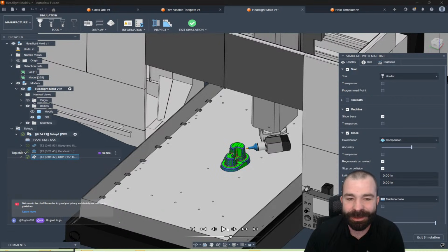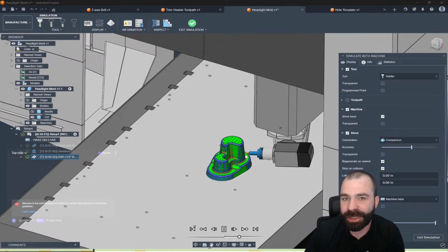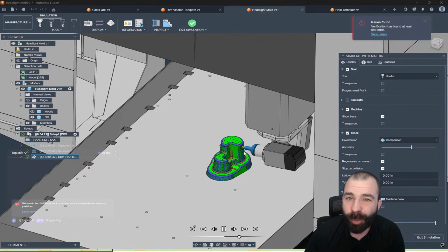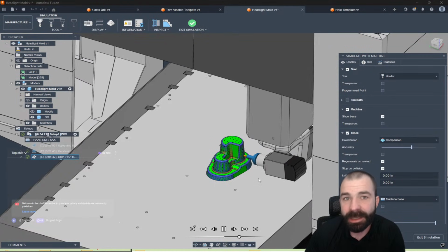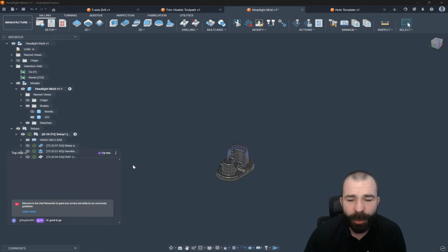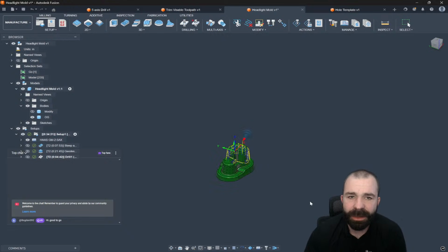We might just need to slow her down a little bit and hit the play button and let it do its natural thing. But what I'm looking for, as you guys can see, is we're not actually going all the way back to a home position, reorientating and coming back in. Dropping your cycle time quite a bit, making your life much better, speeding up, making things easier on the operator. Now, if I go into drilling, I believe we're going to see that here based on our heights tab. As you guys can see, we have a plane kind of setup once again, all built into the software, making your lives much easier. So let's go ahead and shift gears.